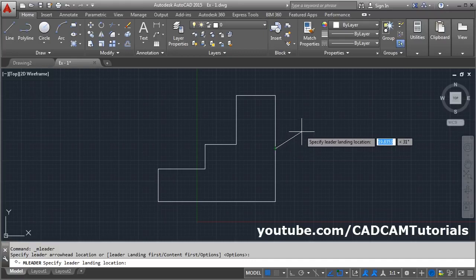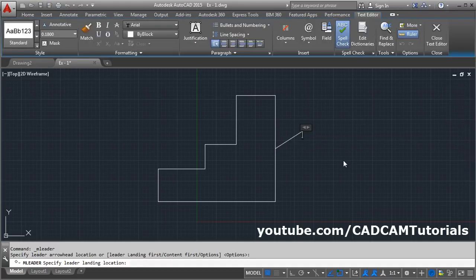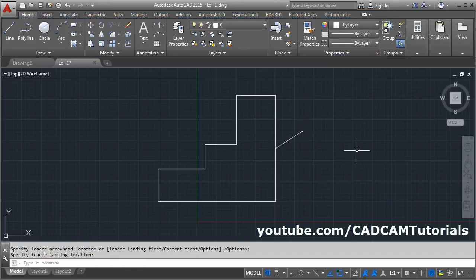Make ortho off if it is on. Then specify the leader landing location. Then give the text that you want to write and click outside. Now this leader is not properly visible.